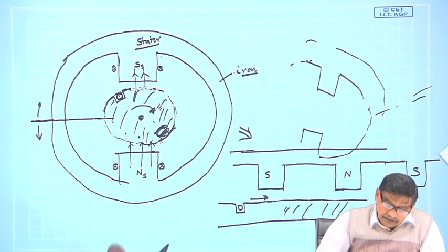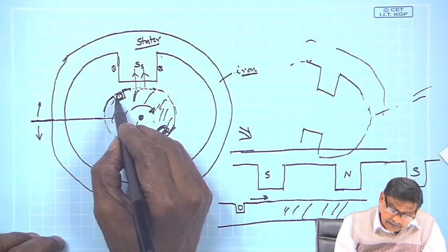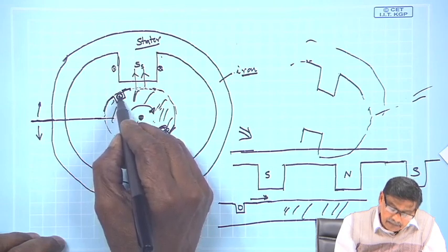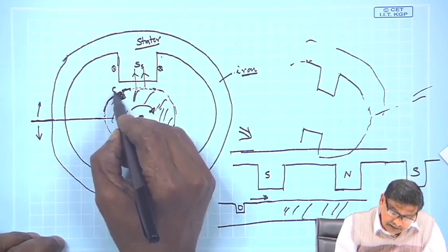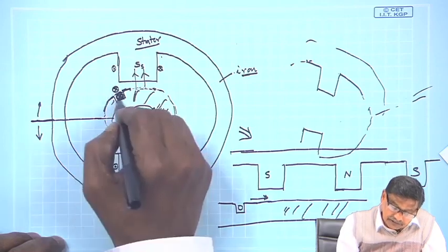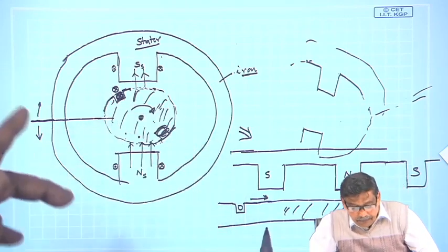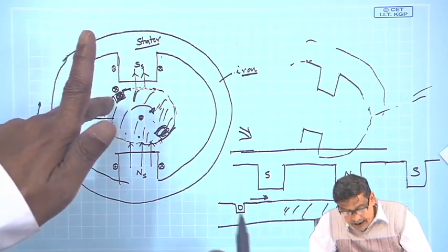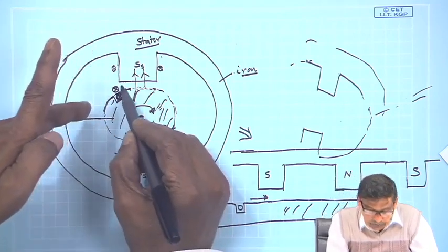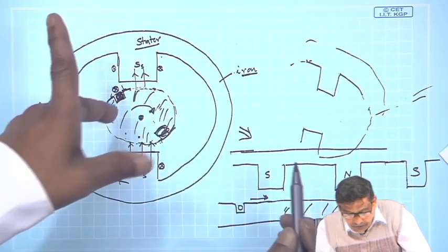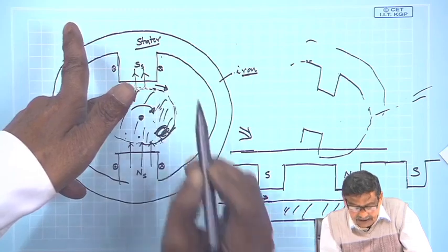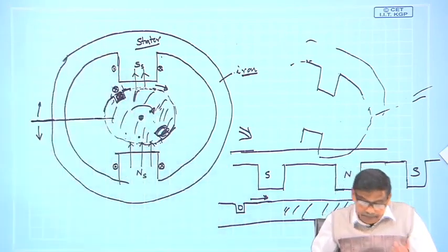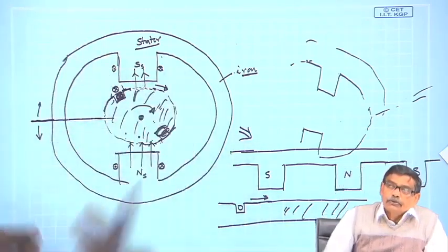Therefore, I would expect, for example, if I pass some current in this direction, it's a cross current I am passing through this, I am so bad. So, this is cross current, suppose this conductor, then this is the current and the field, this is still south pole here, lines of force will go. So, it will try to move like this. So, you will get motoring action